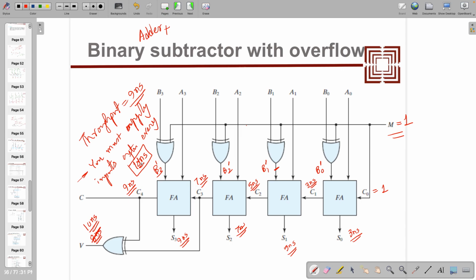10 nanoseconds. Okay, first of all 9 nanoseconds plus this is 1 nanosecond additional, right? From the XOR, so 10 nanoseconds is coming from here. So I am saying for this circuit you have to make a budget. If you have to give the input, how much time after you should repeat it. So that is only